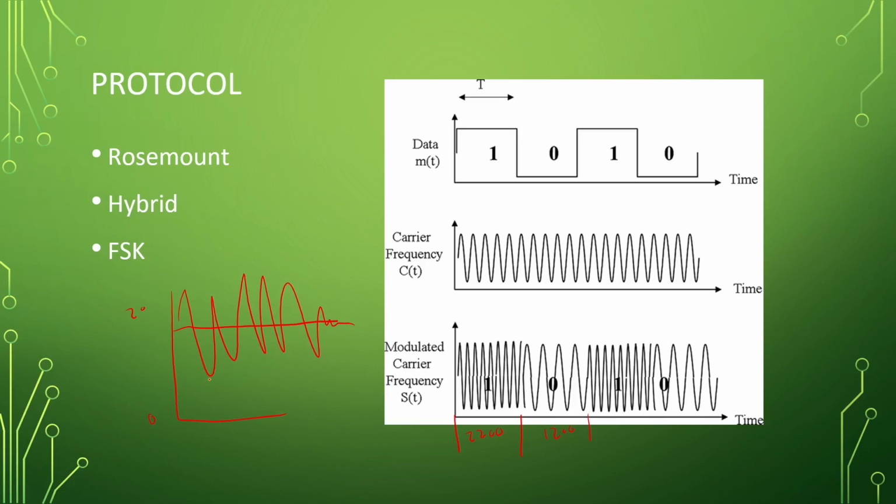So the frequency, the digital side is just measuring the frequency. So it's saying 2200 or 1200 back and forth respectively. And then the analog is just averaging it out, still seeing the same current flow that it would before. So we're not actually changing the 4-20 milliamp signal at all. I mean, technically, yes, it's changed, but based on the receiving PLC, it's not changed because there's nothing different there.